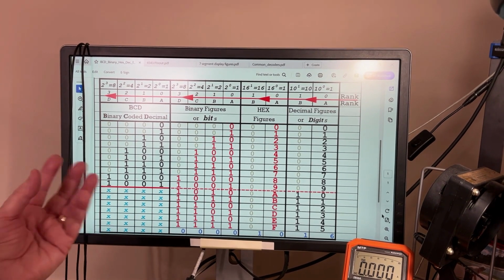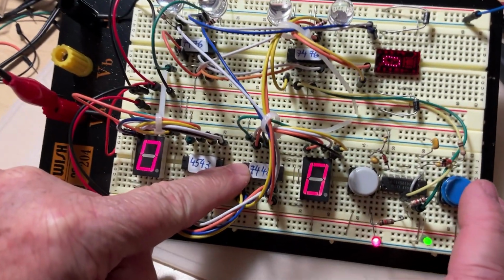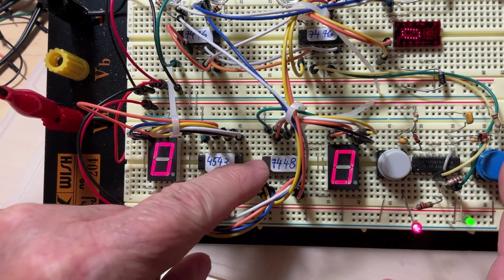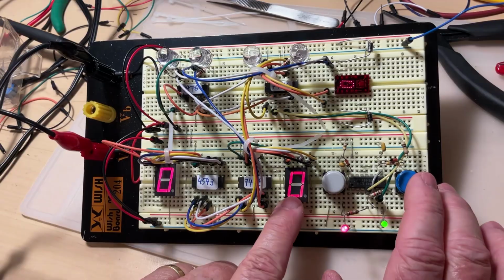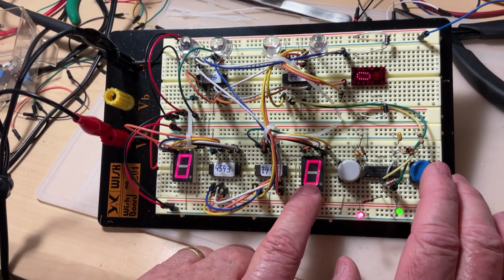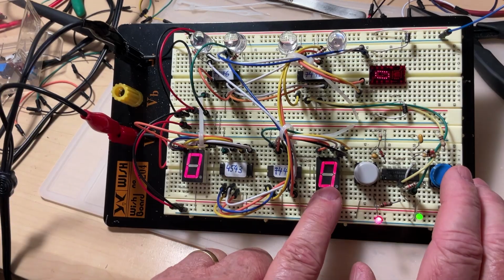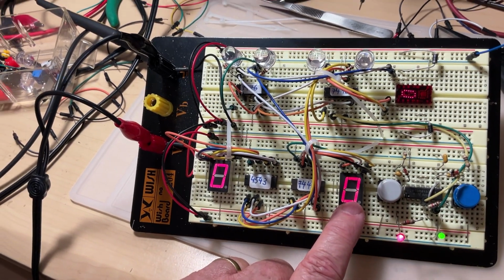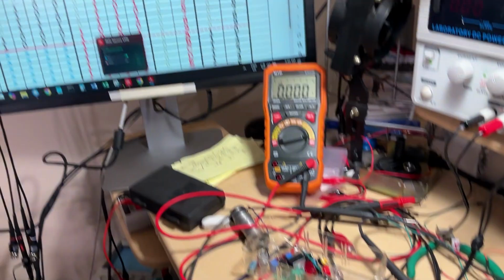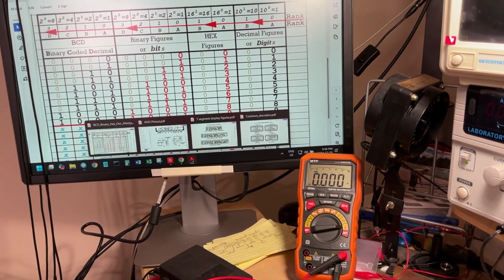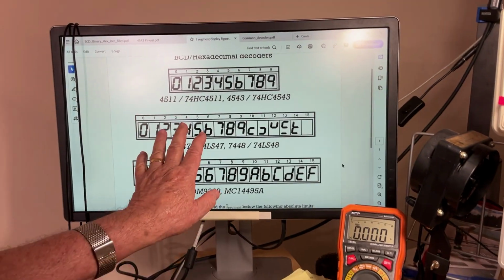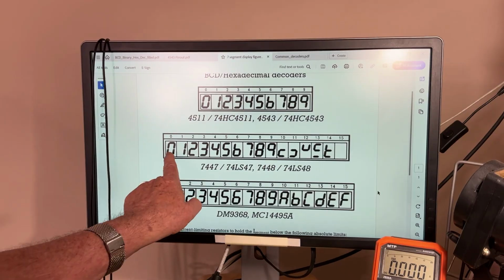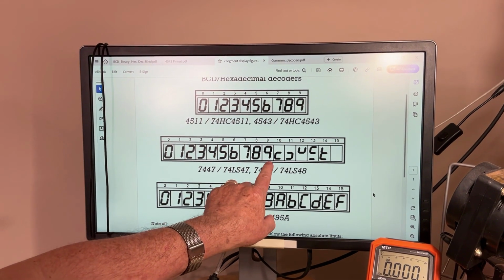However, some of the manufacturers, like the ones for the TTL circuits 7447, 7448, decided to show something, because on the display itself it wasn't possible to show numbers bigger than 9, but they decided to show something though. Just to tell you, these symbols actually represent numbers bigger than 9. And here we are. If you take a look, 0, 1, 2, 3, and so on up to